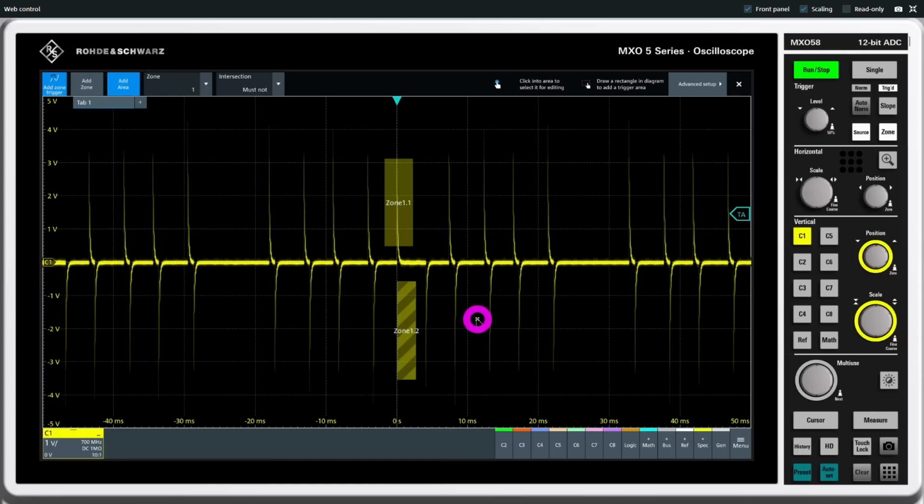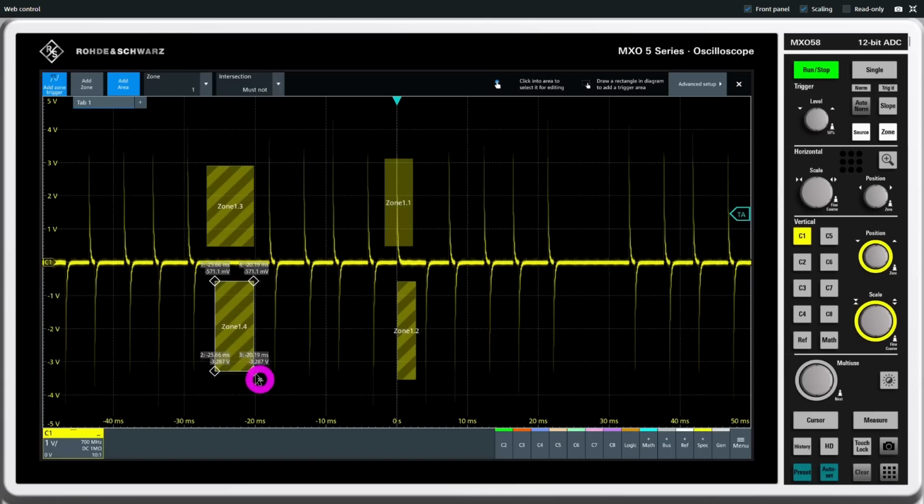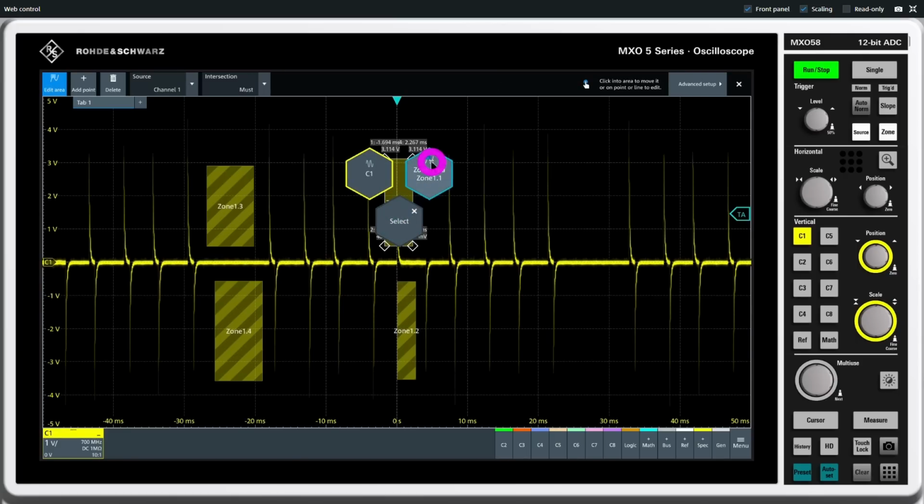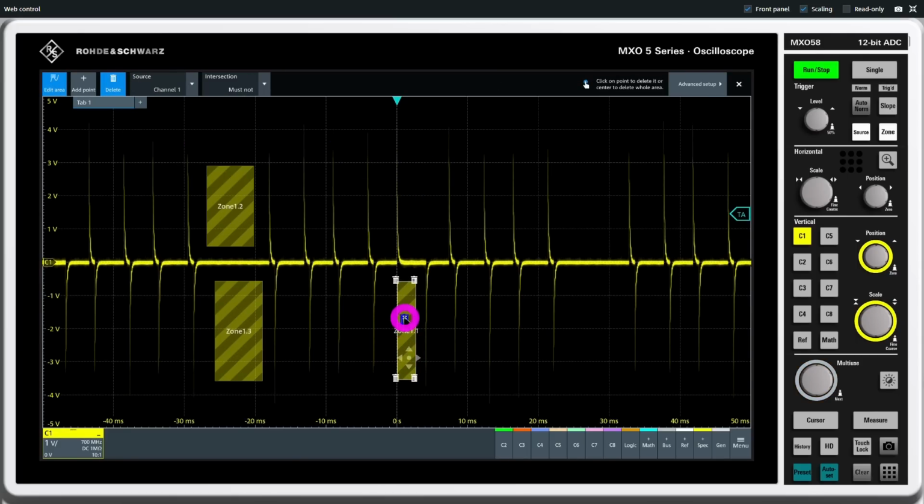Now another thing you can do in this situation is that you can offset the trigger, basically keep these two areas over here, and then say, well, what I really want is to make sure that there is nothing here and there's nothing here. Now this doesn't seem to do anything differently, but now I can go back and erase these ones. And that can be an interesting thing in itself, because if I erase them, I simply get a stable waveform again.